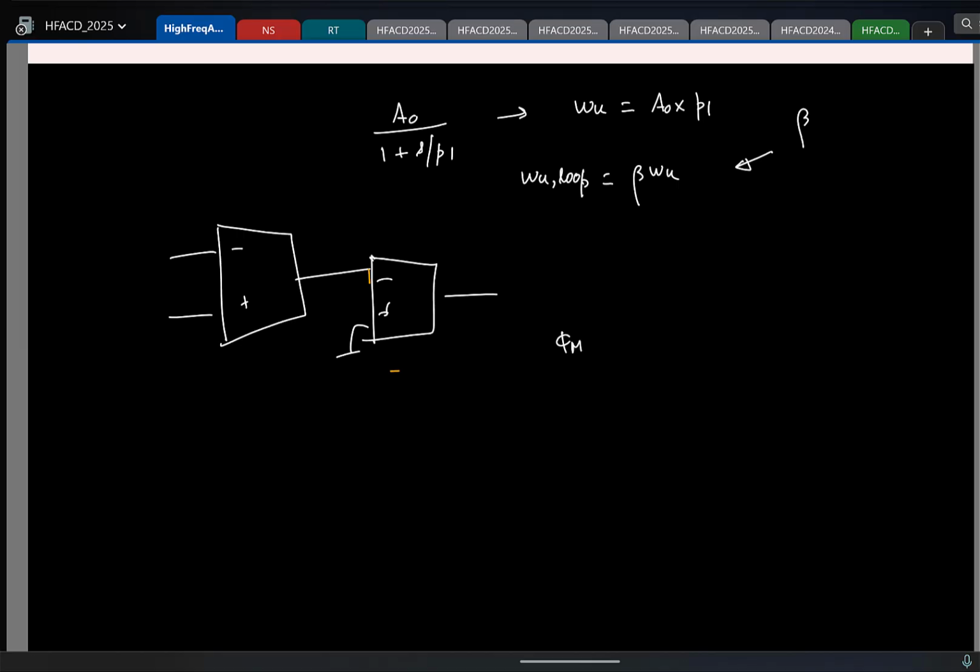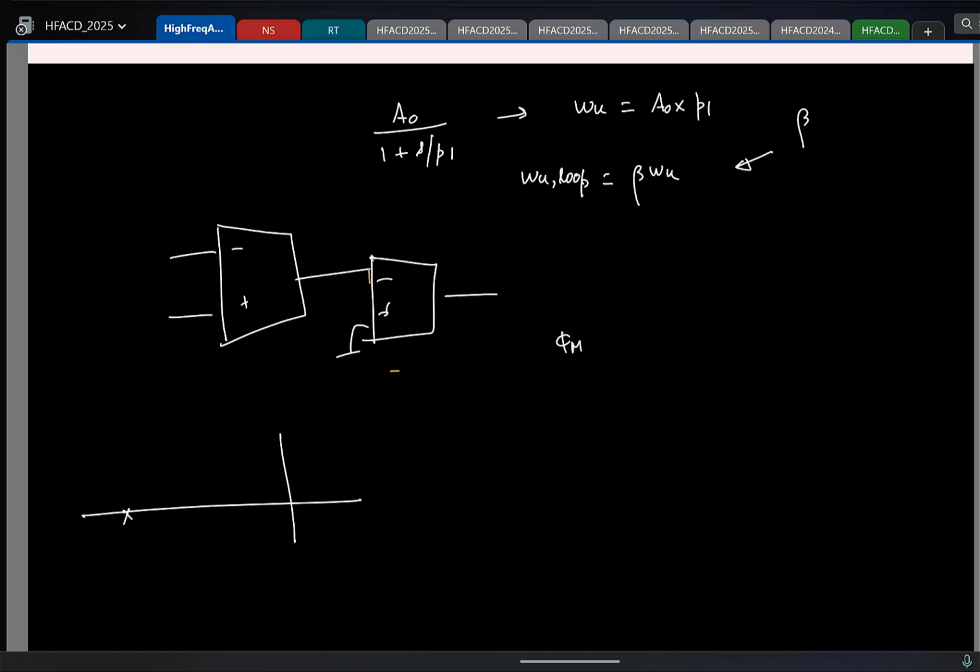And we essentially saw two techniques to make the closed loop system stable. One approach was to keep the open loop poles far apart. Like, as I say, keeping these naughty kids in a class: put one guy here, one guy there, so that they don't interact with each other and keep the class stable. Second is you let them sit close enough, but make sure there is a strict adult sitting next to them so that they fall back in line. The first was the Miller compensation, and the second we did using feed forward.